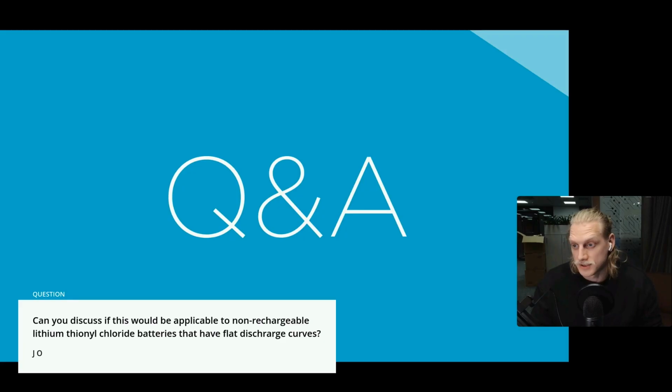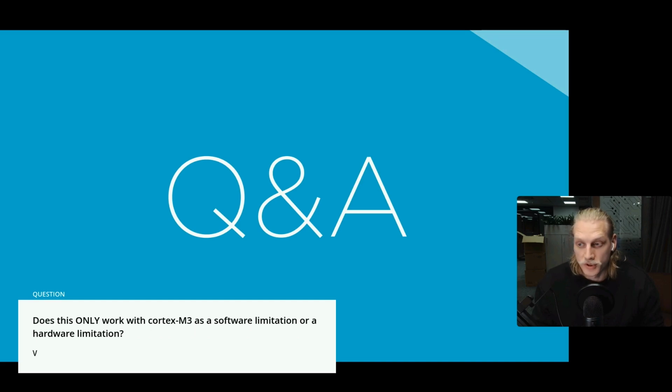So let's just show that question first. I forgot. Then we have another question. Does this only work with ARM Cortex-M33 or M4 processors as a software limitation, or is it a hardware limitation? It is a software limitation, and it is because we are providing this algorithm as a pre-compiled binary.